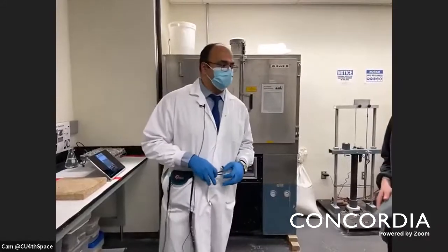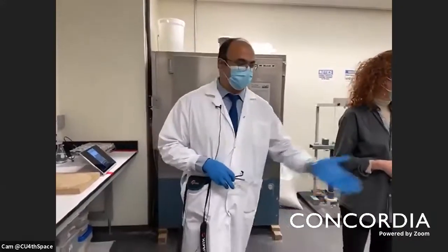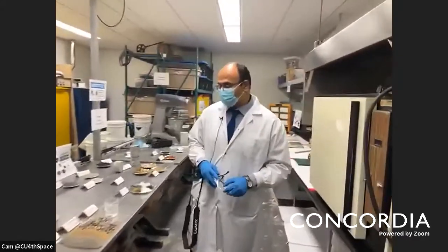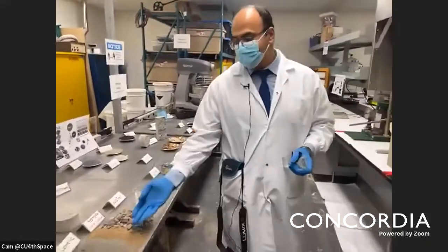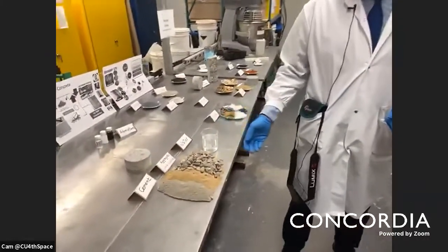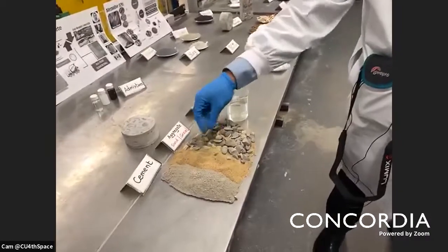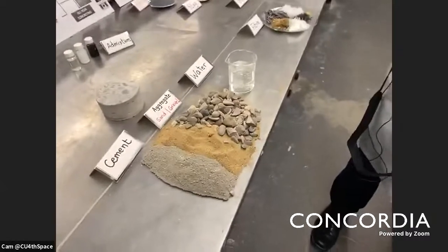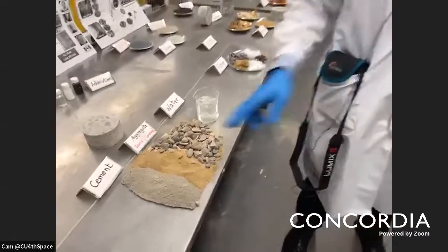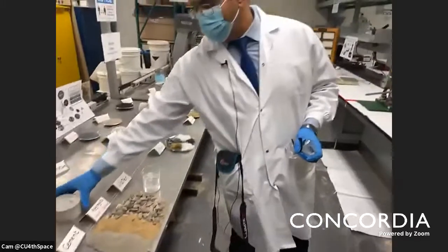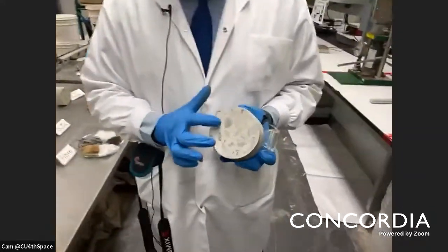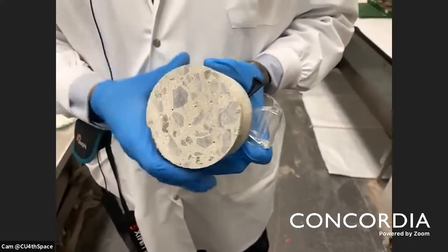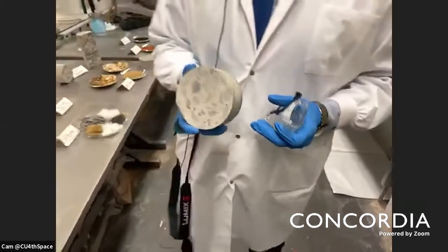Okay, so let us start by giving a brief introduction about concrete, and let us ask, what is the recipe for concrete? As you can see here, we have cement, we have water, we have aggregate, which can be fine and coarse. Once we start mixing the water and cement, we are going to have the binding material, which is going to hold aggregate with each other. And as you can see here, this cross section showing the aggregate pieces, and between them is the binding material or the paste, which is going to hold and form the body for our concrete.